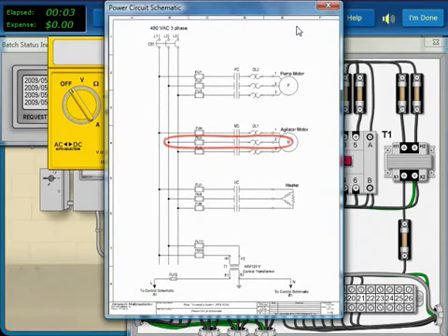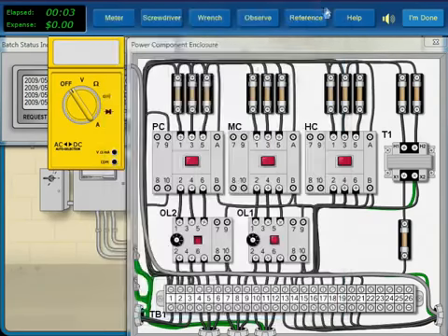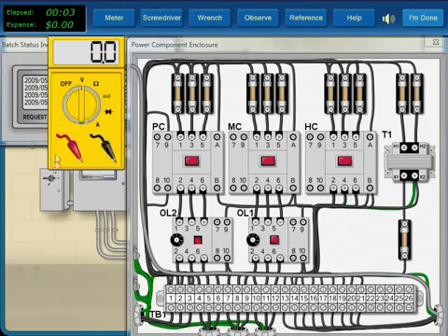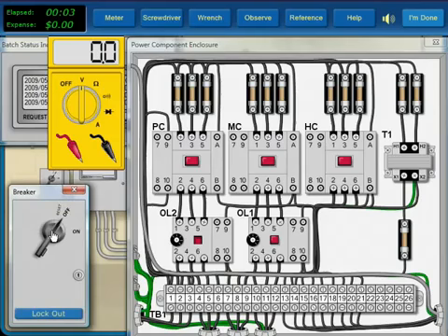In the new problem area, the fuse is now the best place to test, as a blown fuse is an obvious probable cause. To safely test voltage in the power circuit, we open the breaker each time we place the leads. The readings all show full voltage, indicating the fuses are okay.